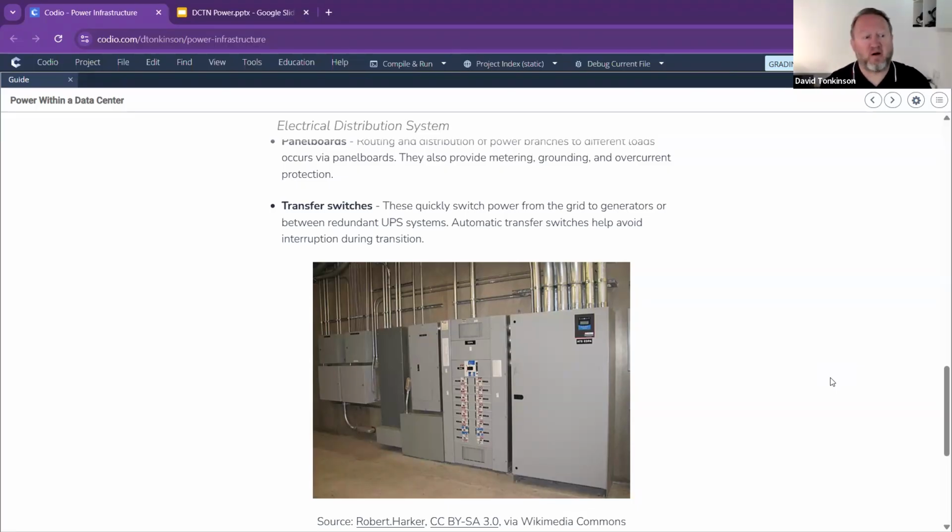So normally what happens with a power failure, and we've experienced this before, is that your initial system will fail, which is the grid power that comes into your data center. The transfer switch will click across and go, right, I've got to go to my UPS, which is our mass of batteries. So the battery pack will kick in. At IMART's main data center, they reckon they could get 30 minutes out of their batteries, and that is it. So if their diesel generators didn't kick in within the 30 minutes, then the data center would be dead. That's your battery storage.